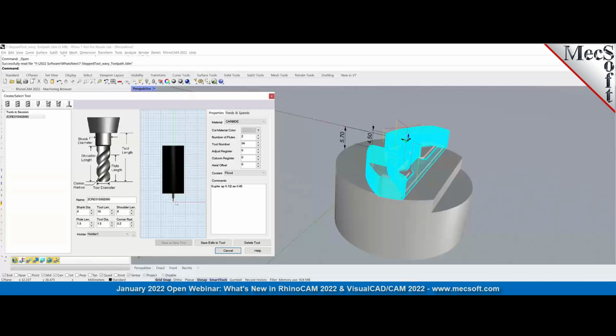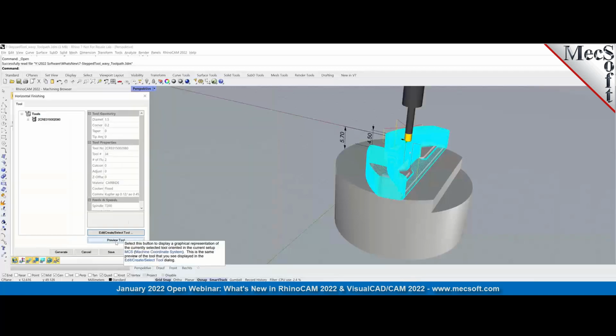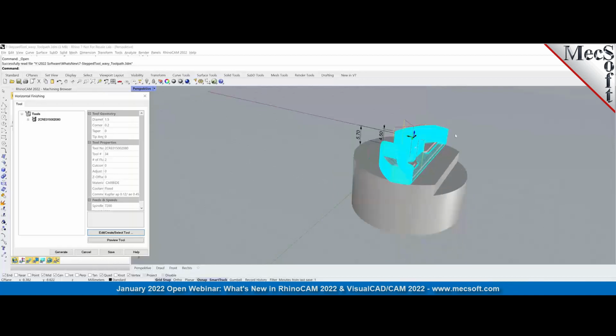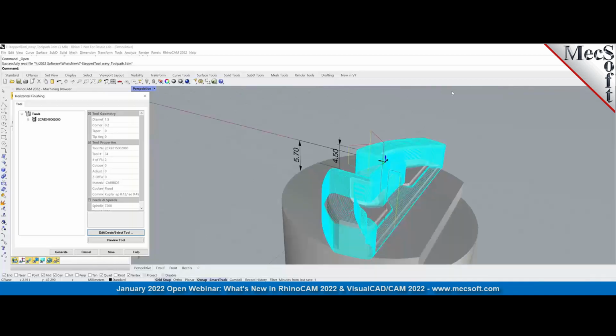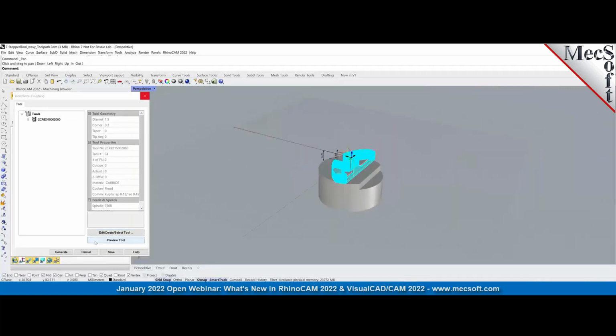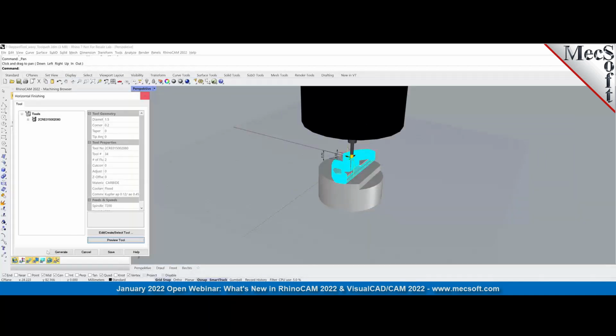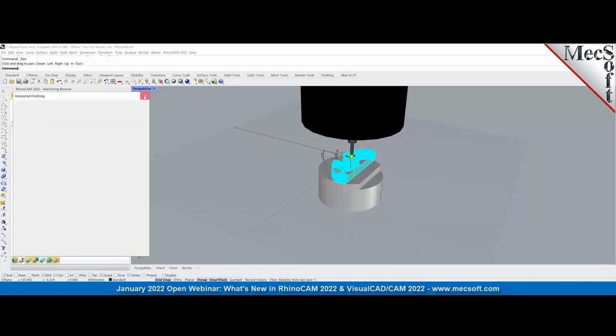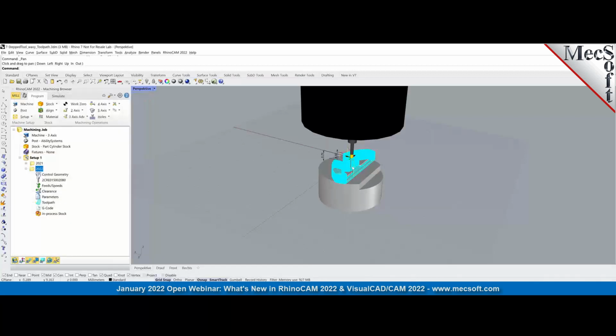So as you can see, the display. You can use this in situations where you have long, slender tools. That's your shoulder for additional strength. Let me get a better display of that into a preview tool. That's the tool holder, and this is the stepped tooling. So this is now completely in all 3-axis operations, you can use step tooling. That's a big change as well. Mostly it's an internal change, nothing in the UI or anything like that.